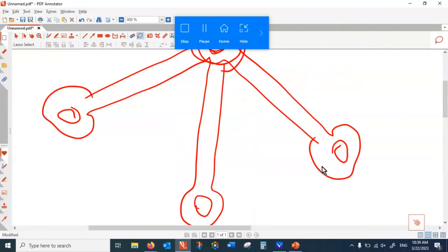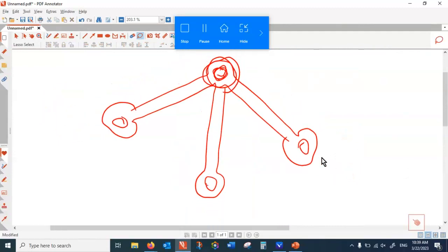All right, can you see now we managed to put three two force members together, and when I put a pin through this one, how the force is applied? The force is not applied to this member, or that member. The force is taken by the pin. So pin is acting like a distributor. So whatever force is applied here, what happens to the force? When you apply a force here at the pin,